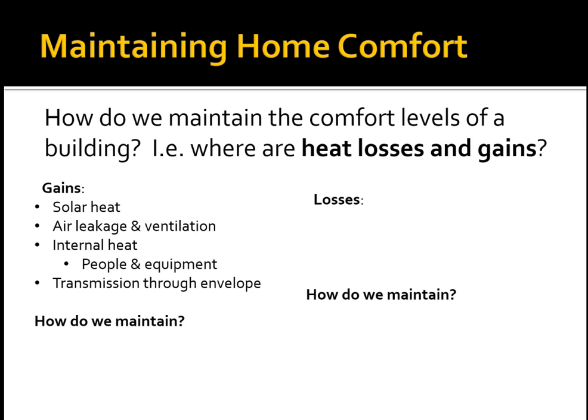People are constantly giving off heat through metabolism, something like 200 BTUs an hour. For any electrical equipment, all the electricity that it uses is ultimately converted to heat because of the second law of thermodynamics. So that's a big part of especially commercial energy use, because a lot of commercial buildings have a whole bunch of lights, people, computers, equipment, and so forth. All of that generates heat, and so that's an internal heat gain.